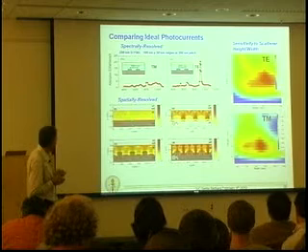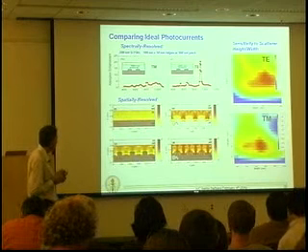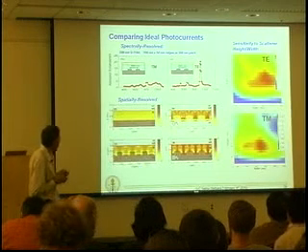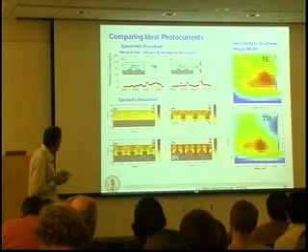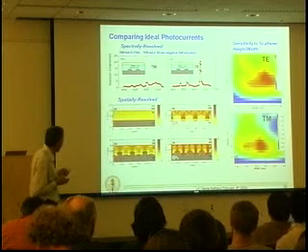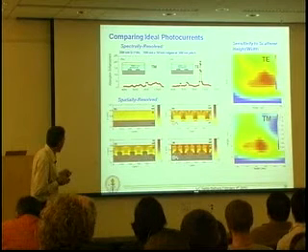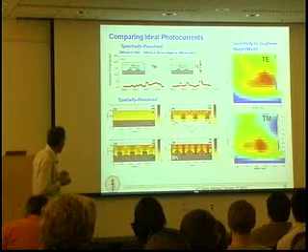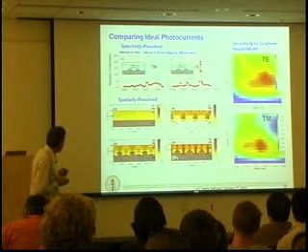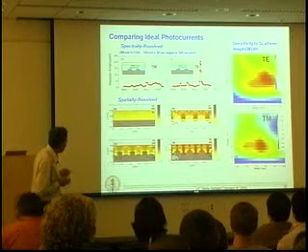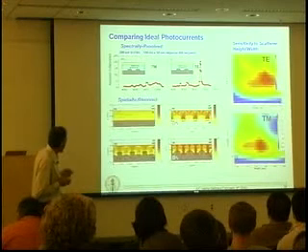And so we can go through on a mode selective basis and determine the incoupling efficiency into different modes, for example, the lowest order TM and TE modes, as a function of the groove height and width and periodicity and so forth. And so essentially what we're doing is we're determining the incoupling efficiency and spectral absorption of these different Bloch modes.